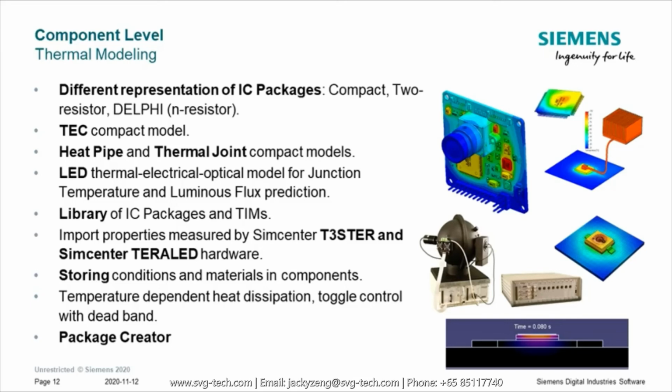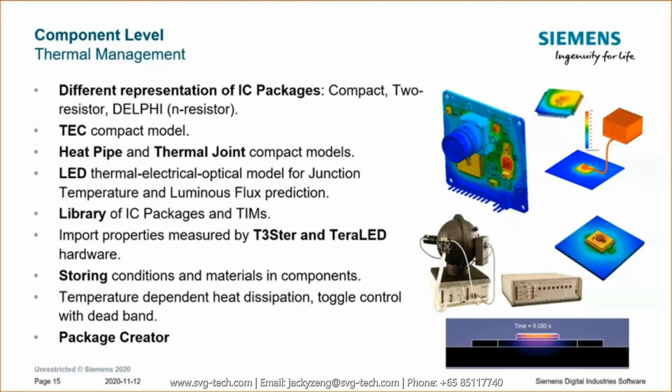So at the component level, obviously there's different ways to model ICs. Adil just took us through a few of them, from compact to resistor to a network assembly approach like a Delphi representation. We have compact models like thermoelectric coolers, heat pipes, thermal joints. There is a nice way of modeling LEDs, which I'll touch on momentarily. Connections to some of our hardware for higher fidelity models that you can use FloEFD to simulate.